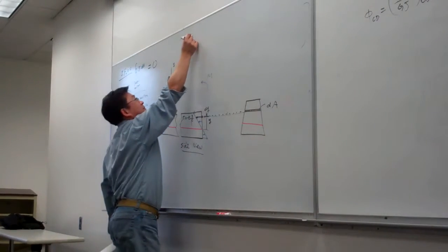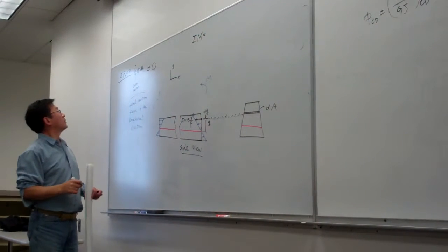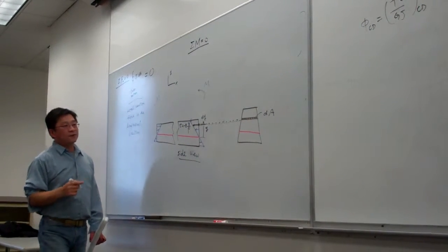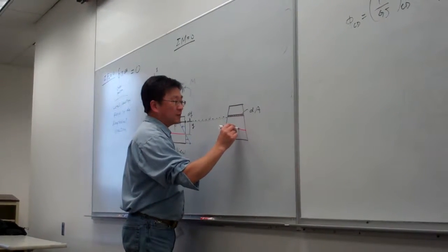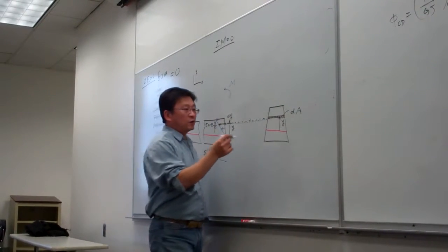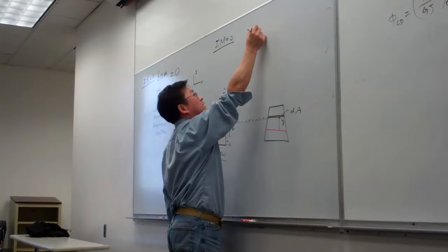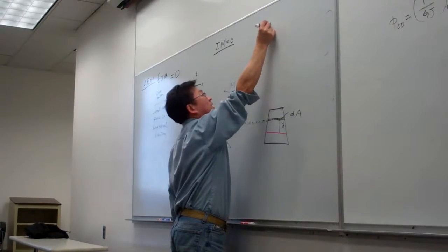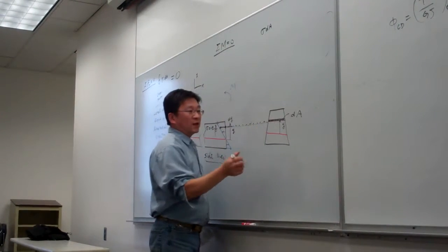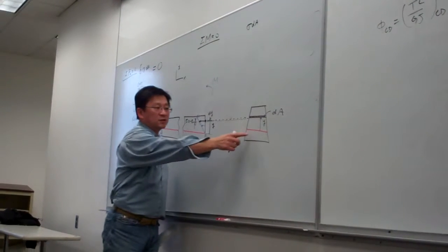The second equation, we take the moment. We take the moment equilibrium equal to 0 here. And for this case, again, this is the distance y. So in a similar way, all the forces applied are equivalent to dF, that is, sigma multiplied with dA, which represents a small force applied on this small strip. And that strip has a distance y from the neutral axis.